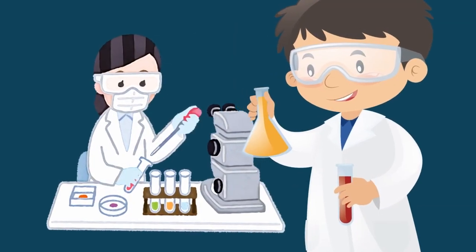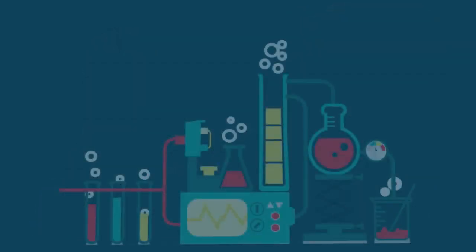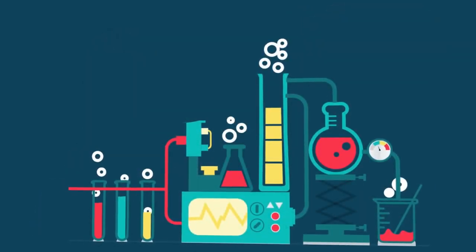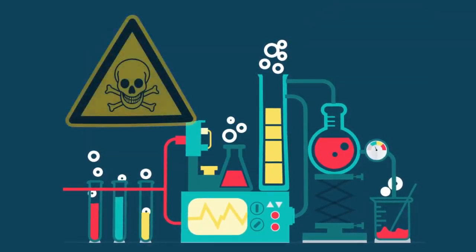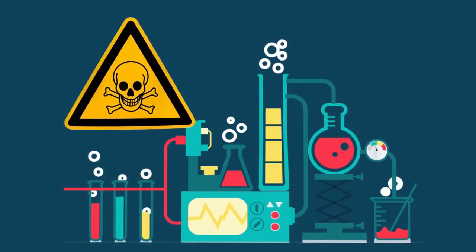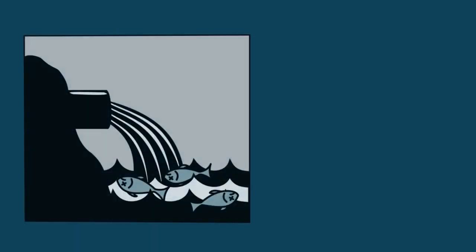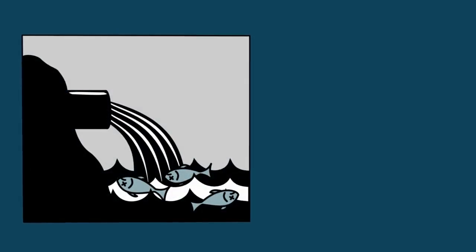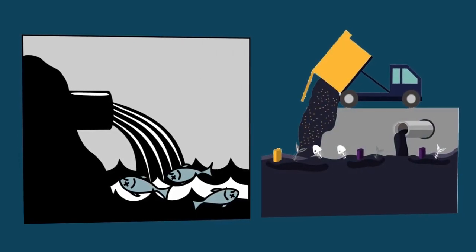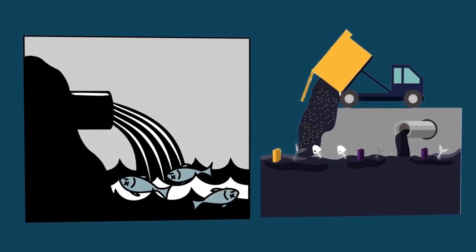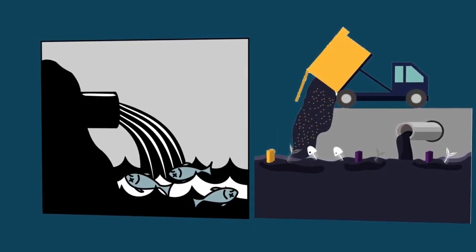The process is advantageous due to fluorine removal, because it offers a low power consumption, a reasonably simple design, and easy operation. However, the use of chemical agents has its disadvantages. During the treatment process, there usually occurs an overconsumption of chemical agents, which means the actual contamination of effluents with other chemicals. In addition, the excessive use of chemicals in combination with a large volume of wastewater leads to generation of waste in great amounts, which adversely affects the treatment efficiency and creates a risk of secondary contamination.